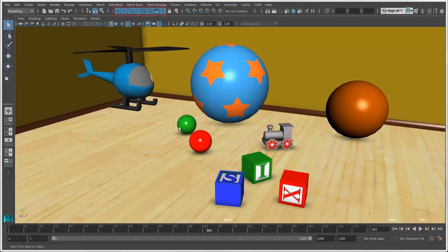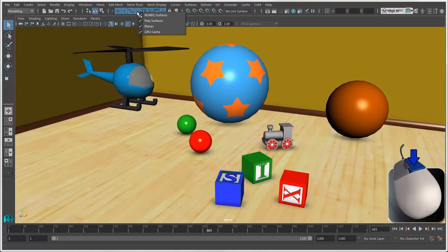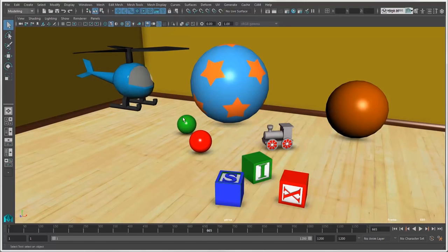The Object Modes icons also let you filter the selection by type. You can click the Object Type filters to decide exactly what you can or can't select with the Select tools. By default, all options are on, so if you didn't want to be able to select joints in a character, for example, just click its icon to turn it off. You can also right-click on the icon to get more specific on each filter's selections, such as not being able to select NURB surfaces objects.